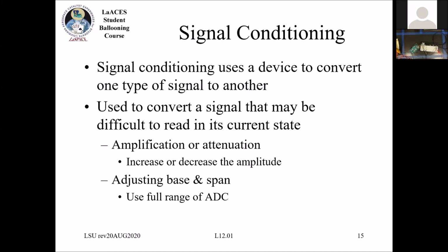So like I said, we either do amplification, which is when we're making a signal larger, or attenuation, which is when we're making it smaller. Or we can adjust basically the base and span. So where the zero is of our signal and how wide it goes to.